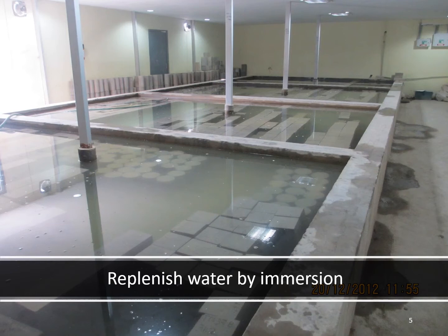At that point also, the curing tank needs to be covered. Otherwise, in summer when the ambient temperature goes around 45, the water temperature also crosses the limits specified by the standards, that is 27 plus minus 2, and you will have a higher temperature.